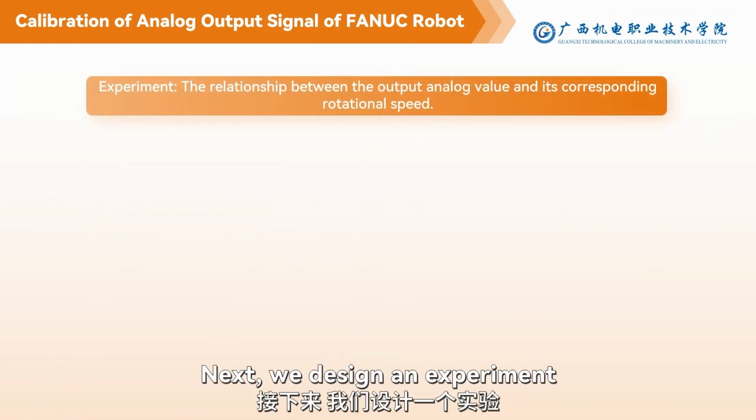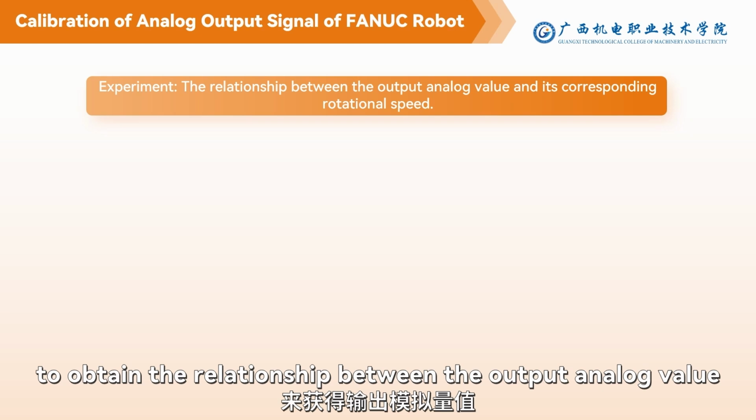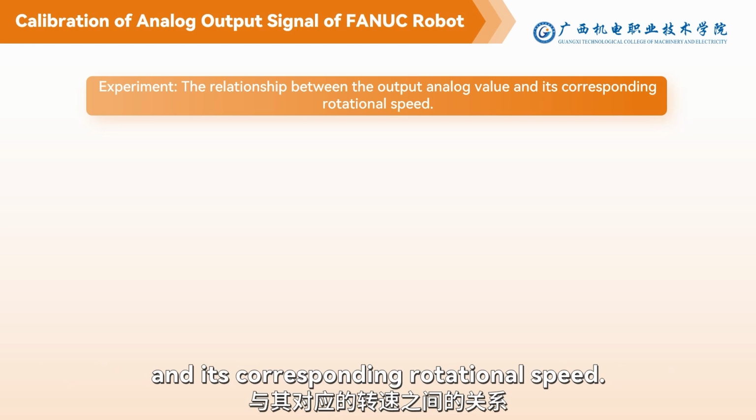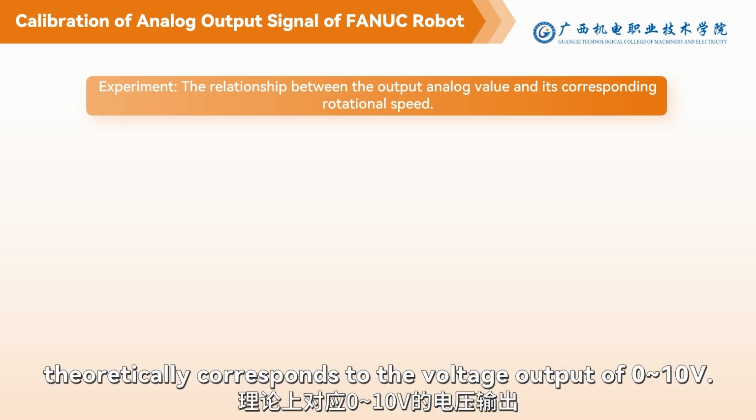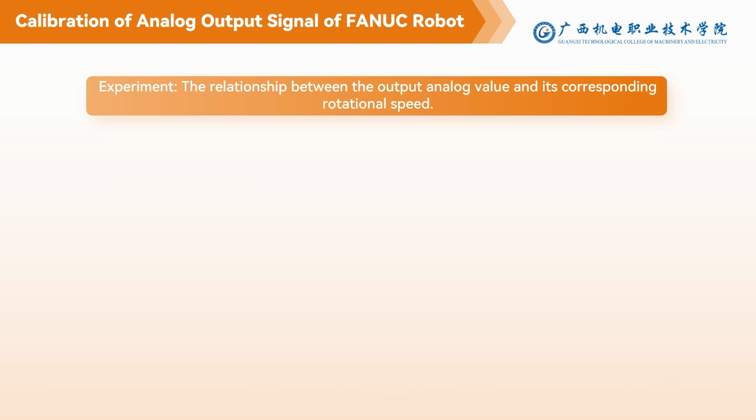Next, we design an experiment to obtain the relationship between the output analog value and its corresponding rotational speed. The KL4004 analog output module theoretically corresponds to a voltage output of 0 to 10 volts.